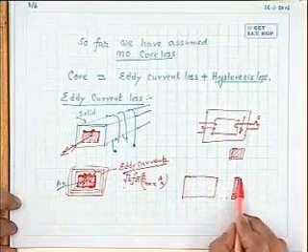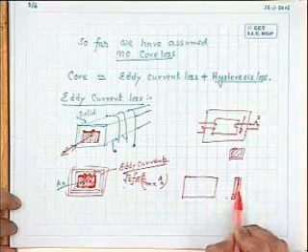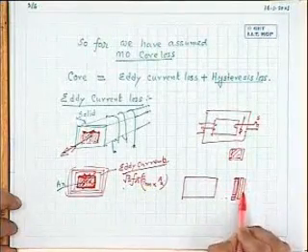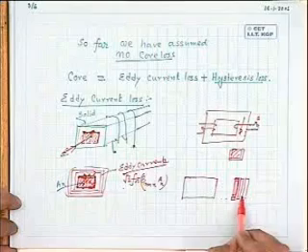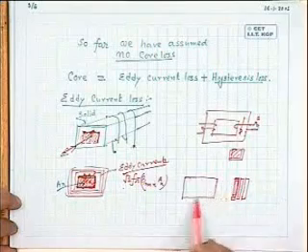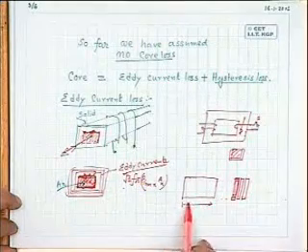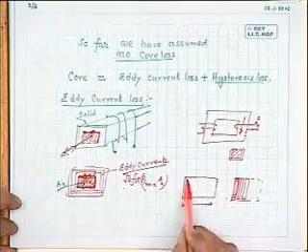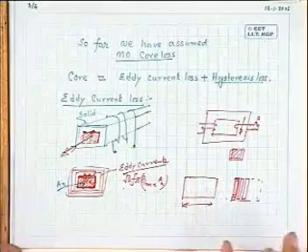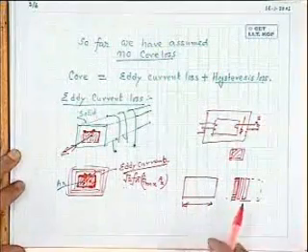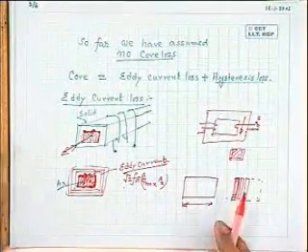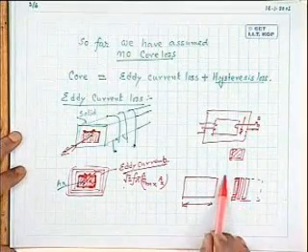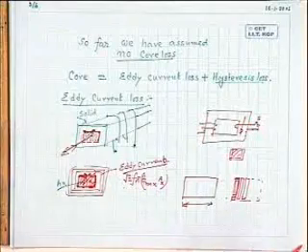So instead of using a solid block of iron, suppose you take several thin plates and stack them together to get this breadth or length, whatever it is. So you can realize this section, instead of using a solid block of iron, by thinner plates.